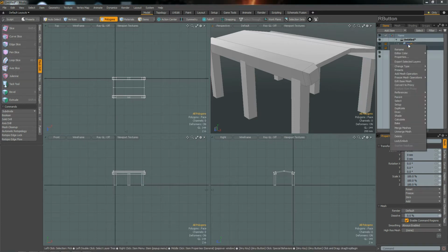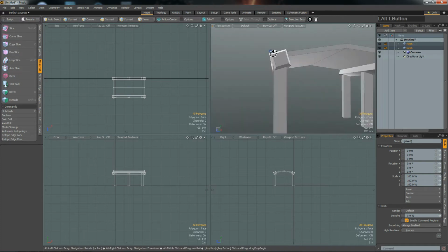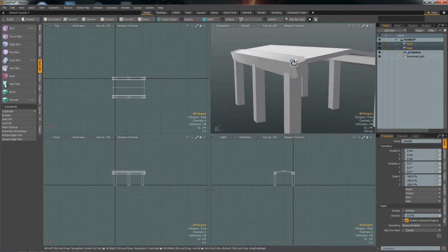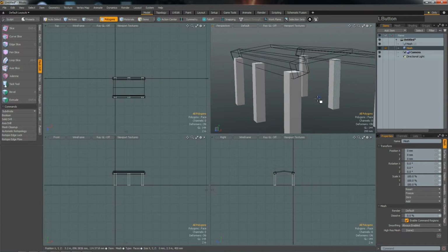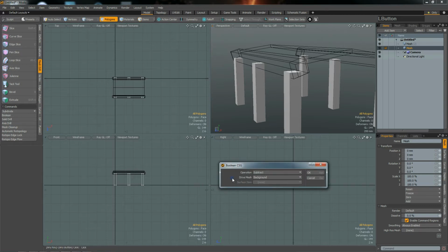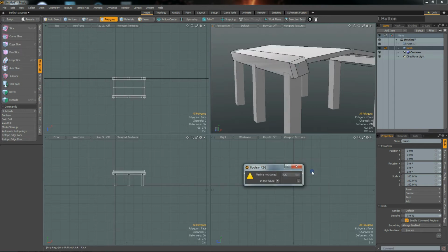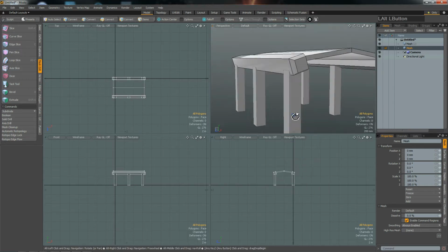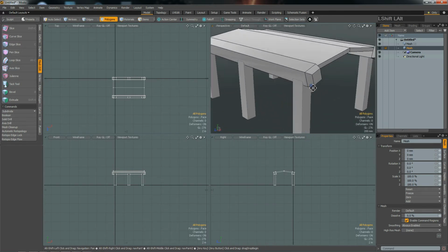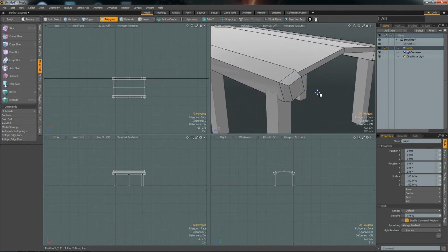So in this version we combine those two together now to one mesh, and I select the first mesh and select Boolean operation. The driving mesh is the background, our other mesh, that is okay. But we don't take subtraction, we take a union. Yep, it tells me it's not closed, which is true because we removed the bottoms. And now we see this, and you can see that the edges here are a bit darker black than here.